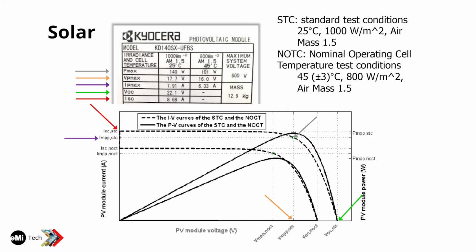This is what the actual curve looks like for a solar module. It's important to understand, mostly for our electrical engineers, so I don't want to spend too much time on it, but basically the concept is that at any given moment of time, these are two different sun amounts and temperatures, and that affects the production of a solar module. And you also want to have a maximum power point tracker that actually keeps it at its sweet spot to produce the most it can as well. So the controls are important. That really helps you get the maximum out of a module. I think that's one important takeaway here, instead of just doing a module without a controller.